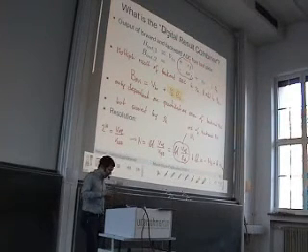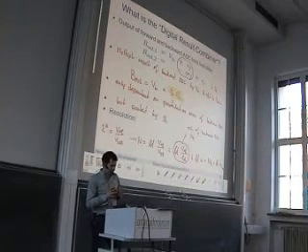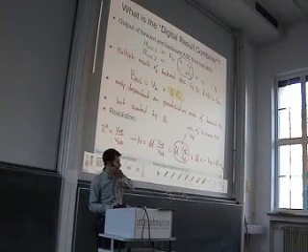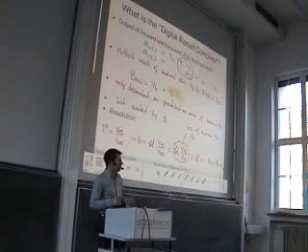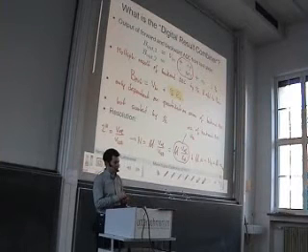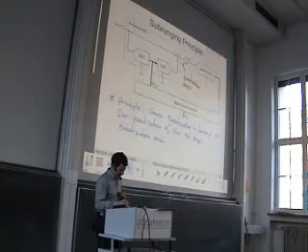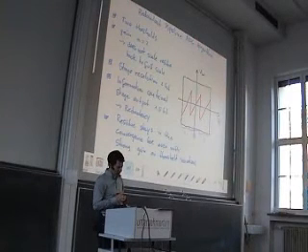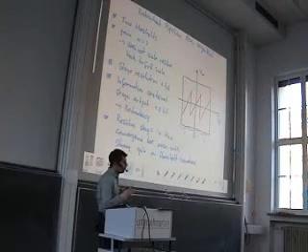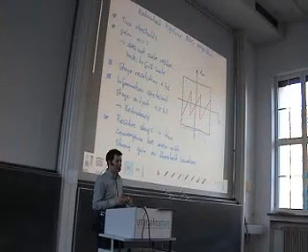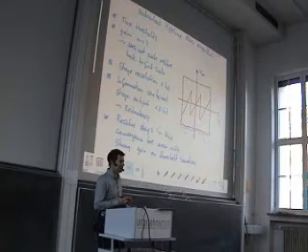So in this two-stage concept, the overall resolution is given by the resolution of the backend plus the logarithm of the gain. So the contribution of the first stage is the logarithm of the gain. So now let me go back. Here we had this slide where I said in such a configuration where we have a gain equal to 2 but 3 decision levels, we get 1.5 bit information out, but at the end the stage contributes only 1 bit to the resolution.